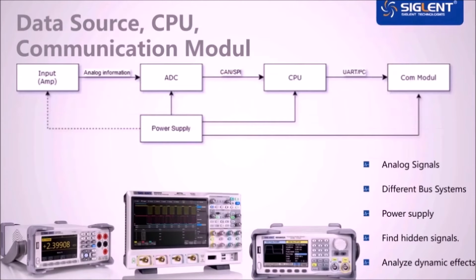This is of course a range that falls out of stream here. We can call it the DC part. At this point, you need classic measurement devices such as oscilloscopes, multimeters, signal generators, laboratory power supplies, a lot of devices for many different tasks. Here, you usually try to build a power supply that is as efficient as possible and therefore saves battery lifetime. Also the power supply should be as low noise as possible. Otherwise, not only the analog data could be influenced, but this can also have a negative effect on the communication module itself.